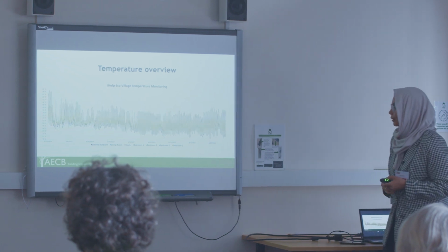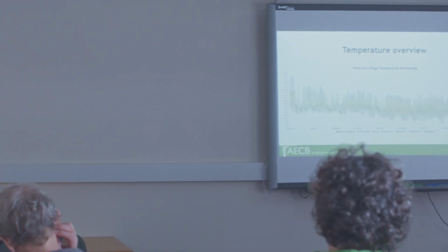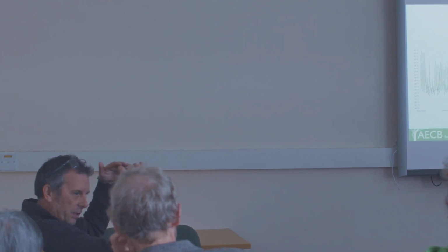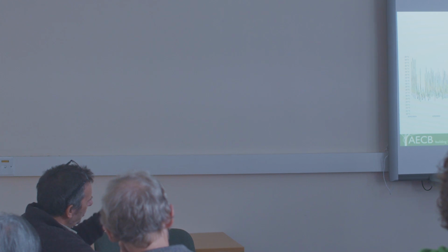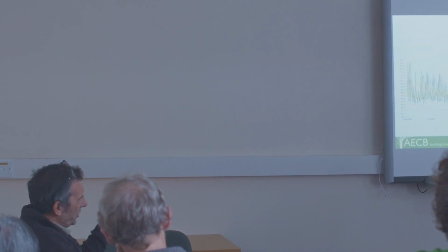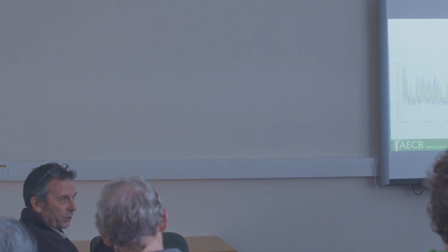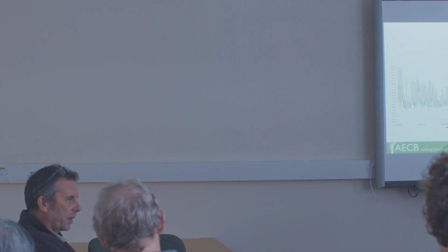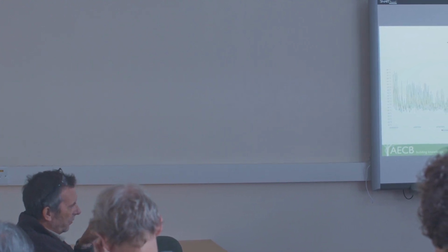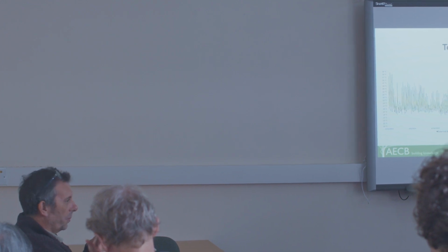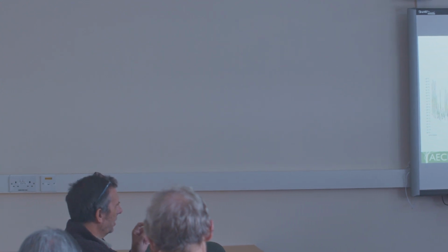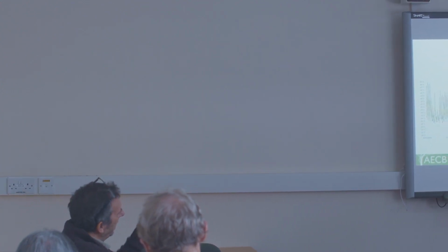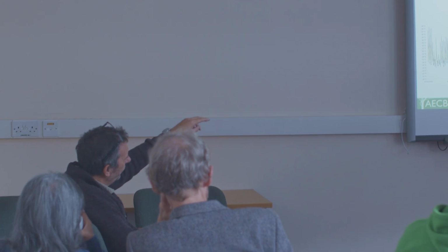And what this graph is also showing is, generally, are the rooms ever hotter than outside, or are they significantly cooler? And do they maximise cooling at the lower temperatures at night time? So the first test unit had too much thermal mass, and it was holding on to the heat too far into the night, which made going to bed uncomfortable. So we reduced thermal mass through a variety of design measures. One of the reasons the windows got bigger was to cut out thermal mass, so we reduced that holding onto the heat into the night, and that design decision has worked.